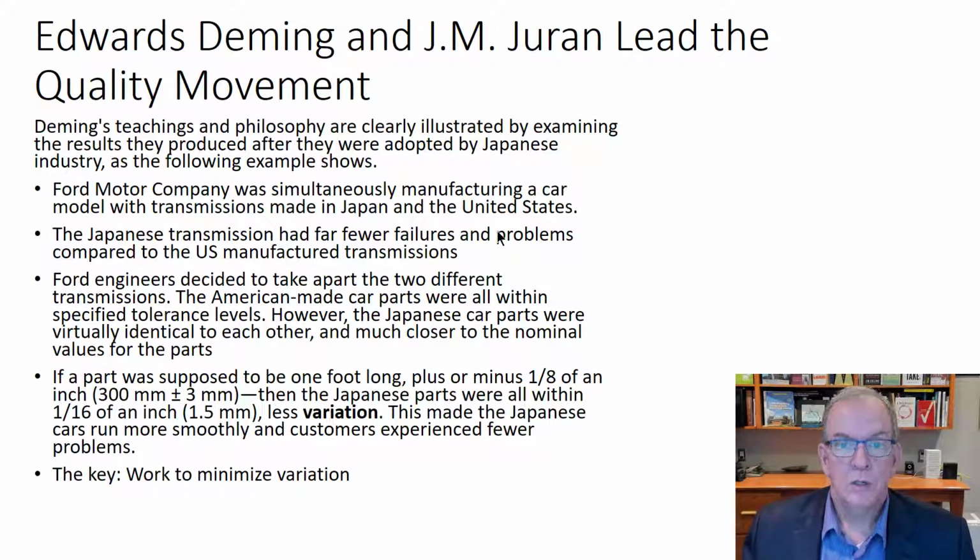Variation in construction causes a lot of problems when people work at different rates and one group moves a lot faster than another group, and then all of a sudden they catch up to the next group. Then you've got that workers waiting for work and work waiting for workers aspect that is phenomenally important in lean construction. We don't want to have workers waiting for work. That's a waste. We don't want to have work waiting for workers. That's a waste. So we want to have a more even flow and less variation in the time frame.